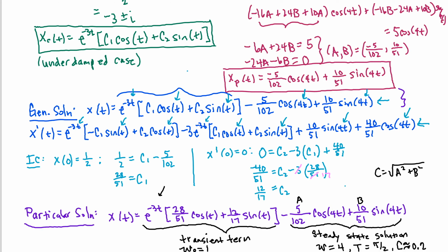Later in this chapter, we're not covering it in class, but if you're interested in looking ahead, there are some other interesting physical situations that, if you're a mechanical engineer, you might be interested in learning about. One is a single blow applied to the base. How does that affect the motion of the mass? For example, if I strike this with a hammer once, I can program that in as a sudden, very large blow to the base, and it's going to drive that base down, and then it's going to allow that mass to have a steady state oscillation eventually.